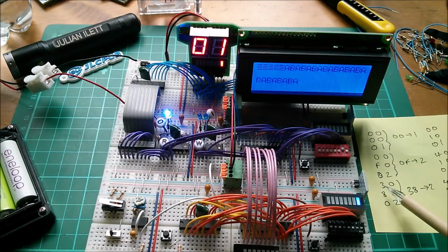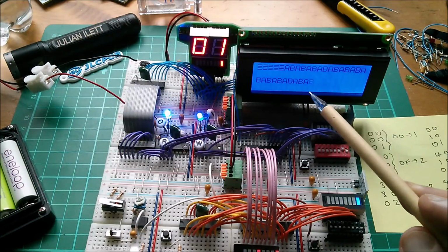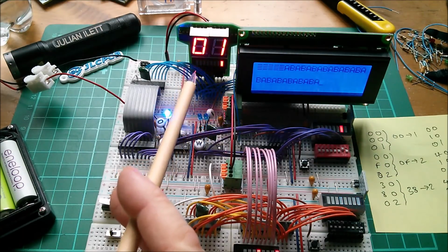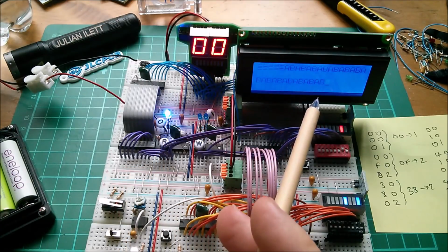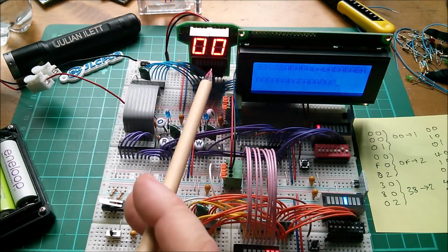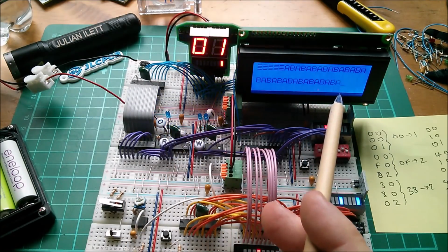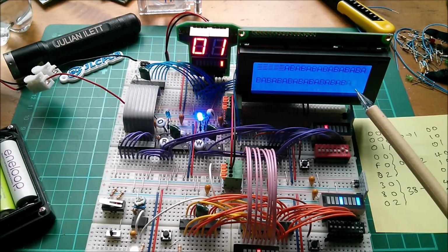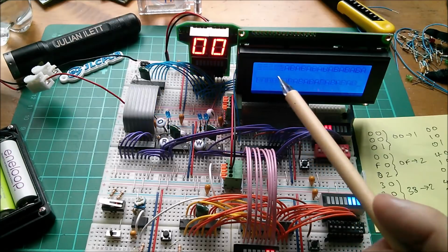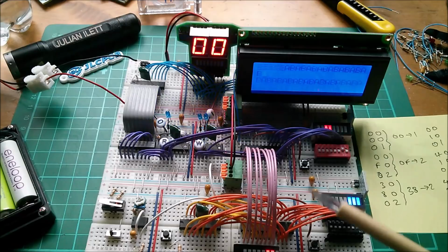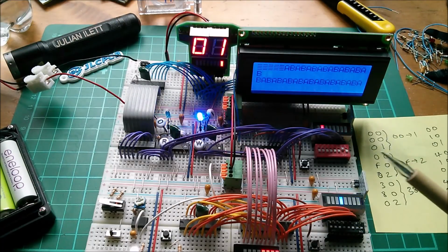So yeah, this is gradually filling up. I can't remember whether 38 sets it to 1 line or 2 line. We'll see what happens when this gets to the end of that line. But yeah, when that's a 0, it's writing commands, and the display fades out slightly for some reason. When this says 01, it's writing data. So when this says 01, you'll see the A and the B appear. Let's just see what happens when that gets to the end of the line. Will it go into lines 3 and 4? Yes, it has. How interesting.